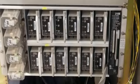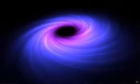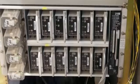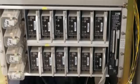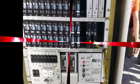Number 1, to check for simultaneous activation of conflicting phases. Number 2, to check for absence of a red indication on a phase that does not have a green, a yellow, or a walk. Number 3, to check for insufficient operating voltage that is usually due to power interruption.